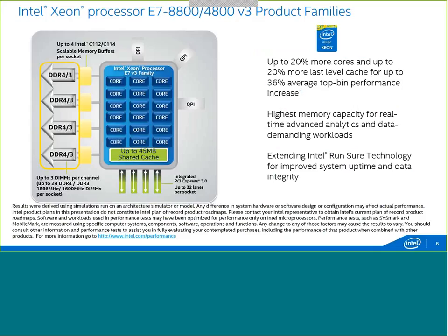It does have a unique feature on the memory. It's the only one that supports this. We're moving to DDR4 for V3 period. E5 only supports DDR4, but the E7 supports both DDR4 and DDR3. You get huge power savings moving to DDR4, speed increase, power savings, and so on. But a lot of folks on the E7 line would rather be able to support DDR3 as well. And here's that third QPI bus coming off that corner. Allows you to have that great 4-socket advantage on the E7.